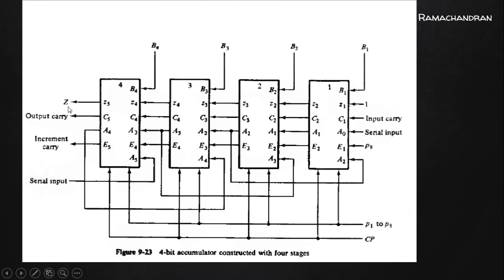Okay, next, for performing our addition operation, the carry flag value from the status register is directly given as an input to the first stage. And after this addition operation, the carry out value, that is C2, is passed to the carry input of our next stage.